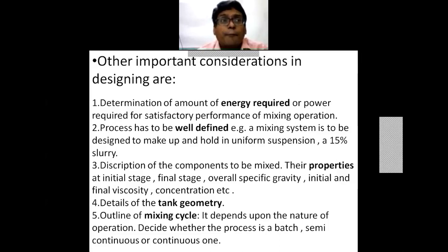Now, in any agitation process, whenever stirring is taking place, uniform flow patterns will be developed, and this flow pattern should be well defined. Then and only then can we reproduce the same quality material. If these are non-defined or very chaotic or very turbulent conditions, then every time there is a possibility that you may end up with a different quality.